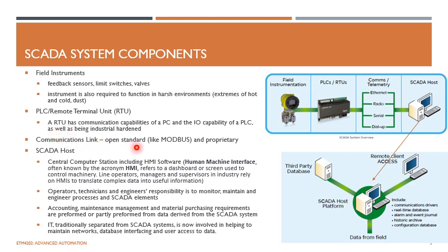Then you have the communication link, where the PLCs and RTUs are linked to the SCADA host platform. So it could be Modbus, Ethernet, or radio, or unguided media, or dial-up lines, and so on. So finally, we have the SCADA host, which is shown in this picture.